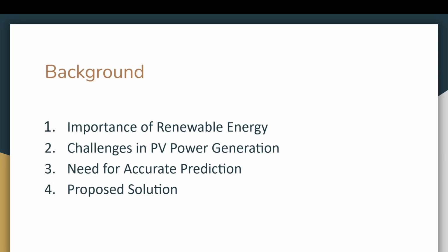The paper proposed a novel approach using a Gaussian mixture model to improve the prediction of PV power output. This method involves clustering prediction errors based on weather conditions to better fit the error distribution. By leveraging GMM, the accuracy and applicability of PV power interval predictions are significantly enhanced. GMM provides a more accurate representation of the prediction error distribution, accounting for its multi-peak nature. Clustering errors based on weather types allows for more tailored and precise predictions.